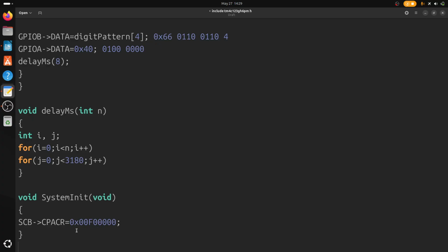What this function says is that the system has this register. It is a 32-bit register. Every register is a 32-bit register. This register is given a value, and F in hexadecimal is written here, and these 2 bits are given 1 to set coprocessor CP11, and this one to set coprocessor CP10.